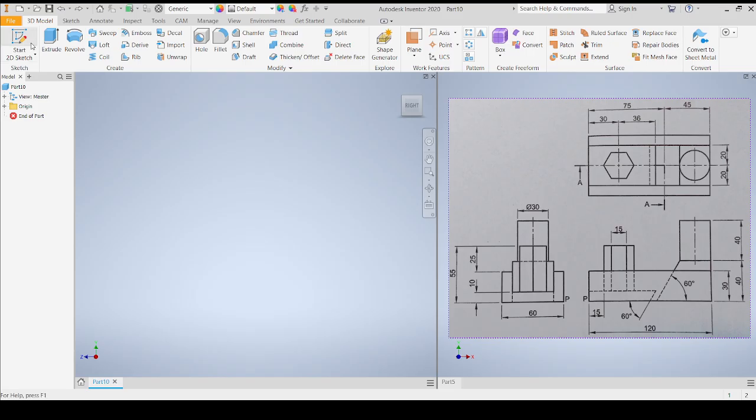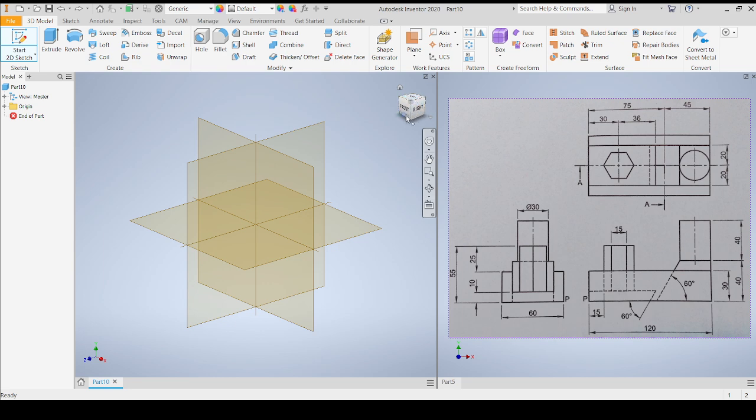So now you're going to start the sketch, right? Remember this cube box right here. It guides you towards which level you must start at. The front view, remember, is the XY plane. The right view is the YZ plane, right? So I'm going to start off with the right view using the guide as the top view.